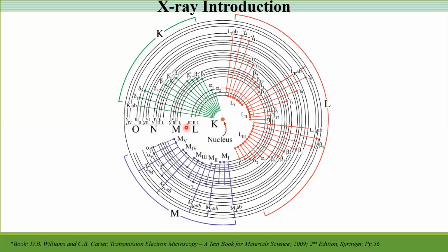So microscopists know this very well. In SEM, you are collecting many signals from specific spot angles. At least in modern TEM with STEM imaging, you are scanning atom by atom, or within a few nanometers by a few nanometers, so you have more chances for accuracy. But in SEM, the spot size is much bigger, in tens of nanometers, so you're collecting many signals within those regions. So with SEM EDS, you cannot claim the quantifications are accurate, and it's always going to be wrong if you're not taking all this into account.